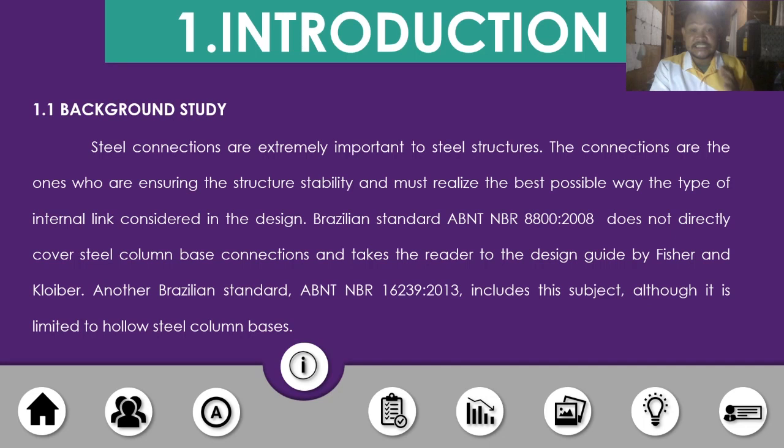So, Brazilian Standard 8800-2008 does not directly cover steel column base connections and takes the reader to the design guide by Fisher and Kloiber. Another Brazilian standard, ABNT NBR 16239-2013, includes this subject, although it is limited to hollow steel column bases.